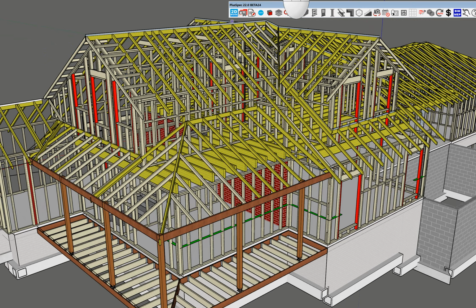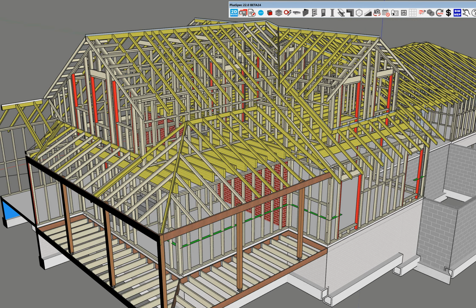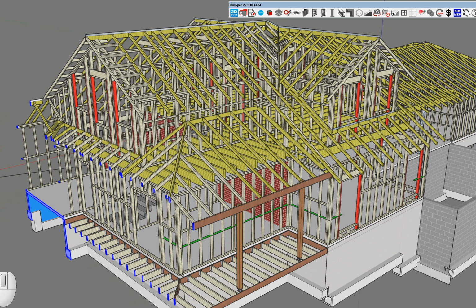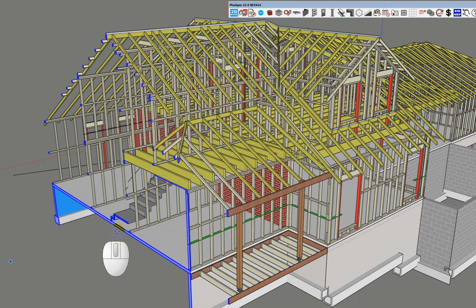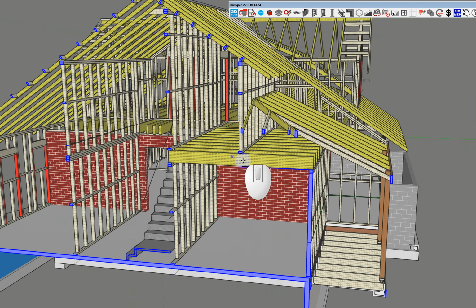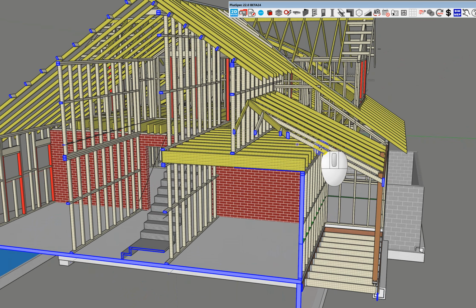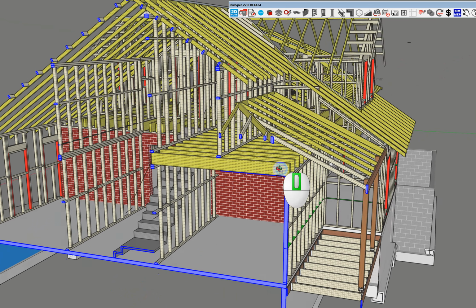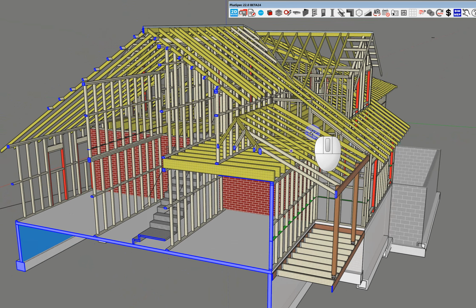See if I can find it, quickly go here, run it here. And what I'll do, I'll just select that and move it. And then maybe this will help explain a little bit more. You'll notice as soon as I get to this area here that the roof load from upstairs is bearing over top of open space, and also the roof load from here, which isn't too much because we will put something on here to hold that section of the roof, but you've still got weight there from there and there.